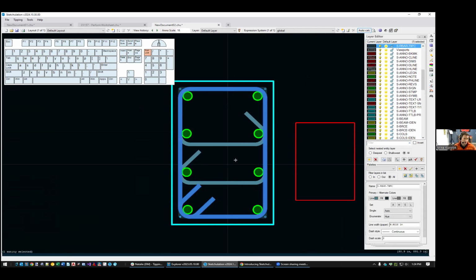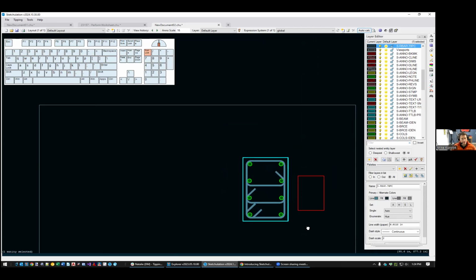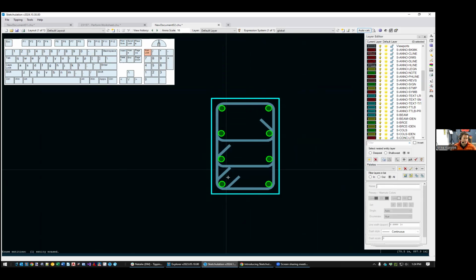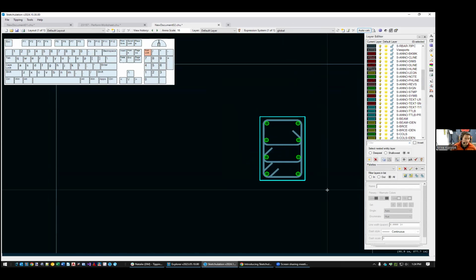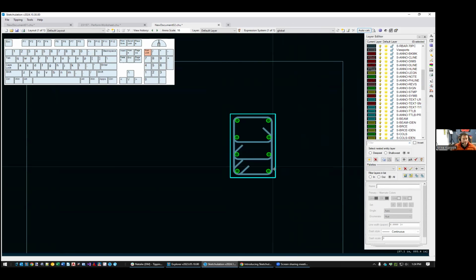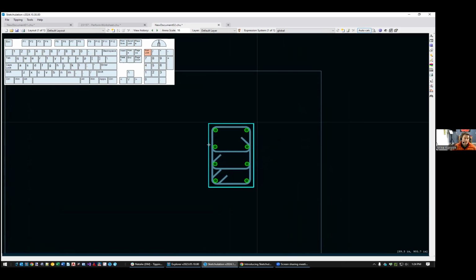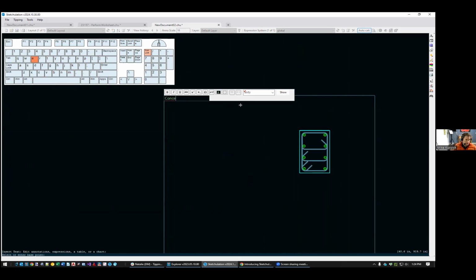You see the rebar in elevation is the true size of those bars, which we really believe in, to make sure you're getting the full visual realization of what you're drawing. The command is designed to meet the ACI rules with the ties and things, so it should be a reasonably good column to start with. Right now, all we've done is basic drafting. It's a fancy drafting thing, which is kind of nice, but what we want to do is the fiber section analysis. So for our calculation here, I would normally start with a title, concrete column or something.